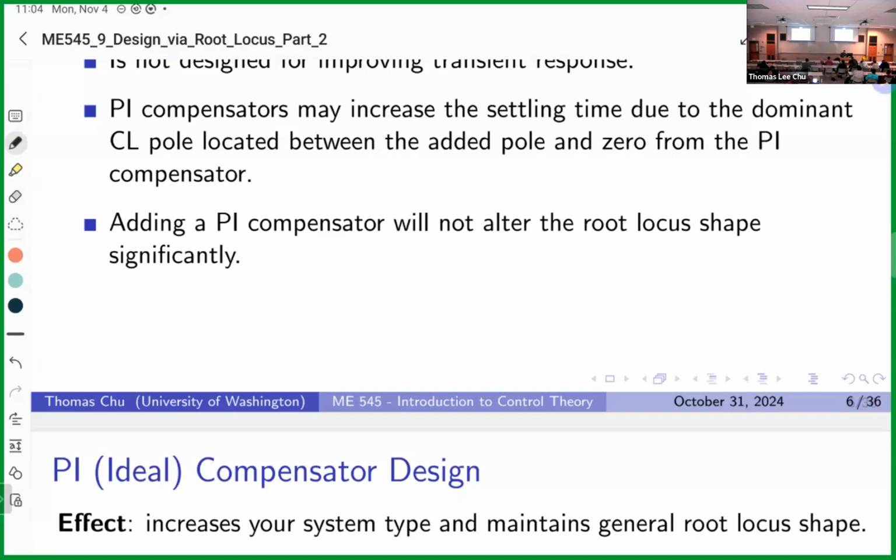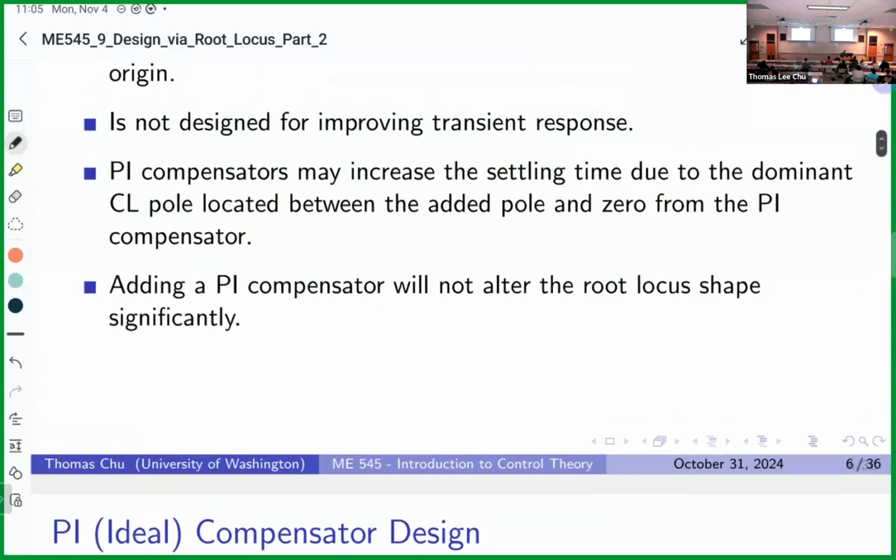Yeah, so exactly. So we add PD and PI because PI won't really change that peak you see. The time to get to that peak will more or less be similar. And then PD will then reduce that peak time, but it won't really fix the error part. PI comes in and will make the error go to zero or make an infinite error go to constant. That's the role of the PI. So the whole purpose of the PI compensator is to increase the system type by one.